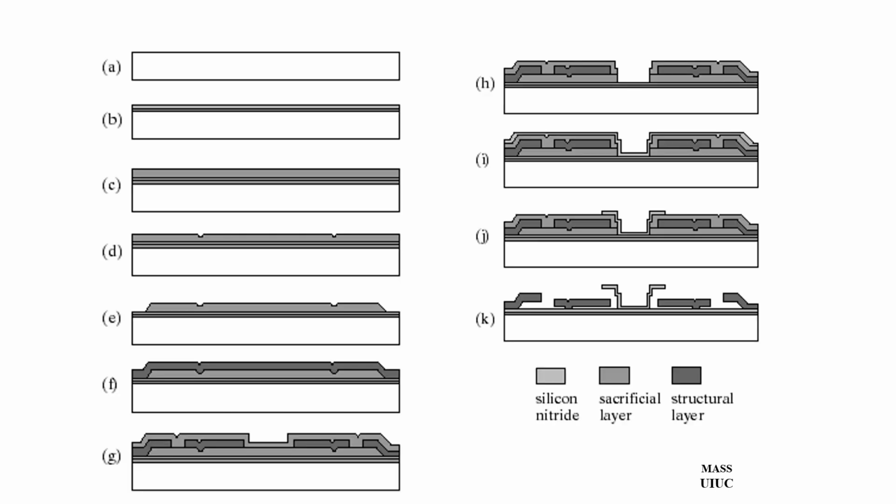Now you can make it more complex. For example, you can add a dimple at the bottom of the rotor so the rotor does not get stuck to the substrate very easily. And one of the ways you can do it is to add a sacrificial layer, but partially etch away the material instead of completely etching. So this is an interesting feature, but it requires timing control of the etching process.